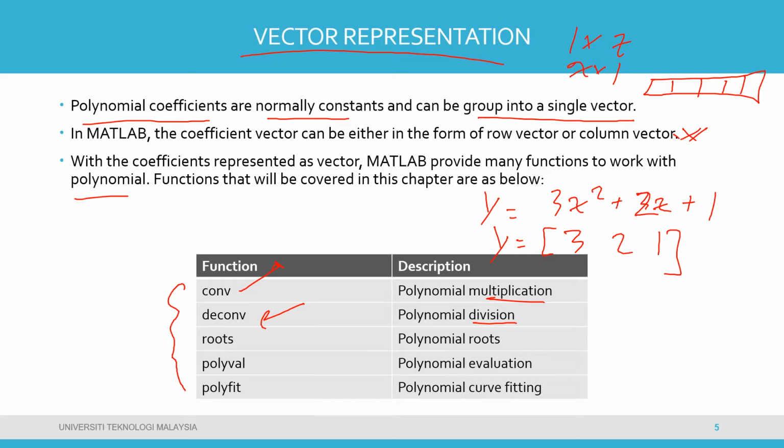And maybe for example you have z, another function or another polynomial. So if you want to multiply y multiplied by z, you can use MATLAB, just write conv y z. And if you want to divide, you can use deconv. Okay, so deconv if you want to divide.